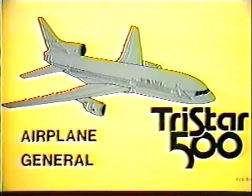-500 airplane general differences. The maximum weights for ship 724 when it is being operated as a -100 airplane are: taxi, 468,000 pounds; takeoff, 466,000 pounds, international operations; 430,000 pounds for domestic operations; landing, 368,000 pounds; zero fuel, 338,000 pounds, subject to certain conditions found in the limitations section of the pilot's operating manual.